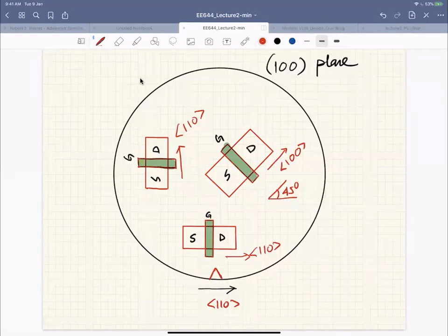Velocity comes from the mobility of electrons, and mobility depends on which direction the electrons are flowing, that is, which crystallographic direction they are moving in. So people do a lot of tricks. They also change the layout. You could tilt your layout so that the electrons will have better mobility, so the current will be higher. So you should know these things.